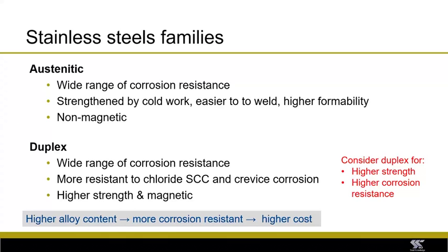And the duplexes, well, you'd think about using a duplex if you've got an application where you can exploit the higher strength. So not if your design is going to be limited by serviceability, deflection, for instance, but if it's going to be limited by strength, then you'd be good to think about a duplex stainless steel. And as you would expect, the higher the alloy content, the more corrosion resistant and the higher the cost.